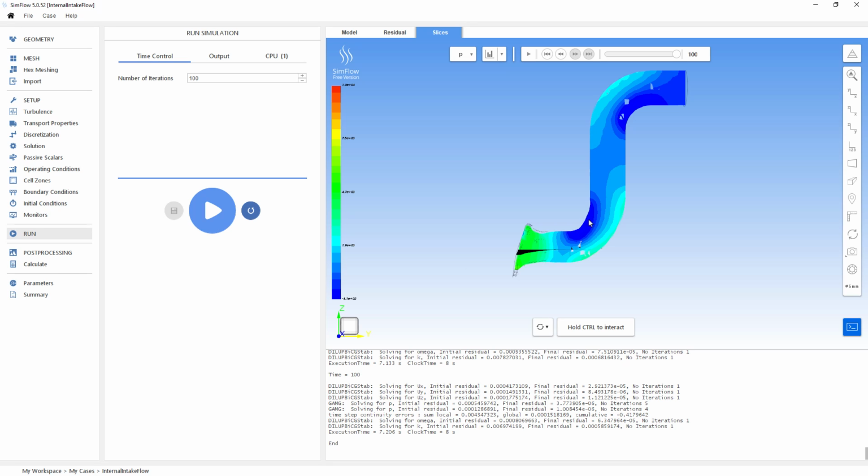And then what we're seeing here is, on these 90-degree corners, we're seeing these low pressure areas and high pressure around the larger portion of the radius. And this would tell me, as I'm looking at it, that I should not use 90-degree bends, but instead make maybe a 60-degree sweep up if I can.